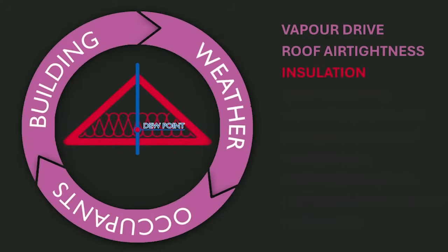As this is influenced by both the temperature gradient and the vapour drive, the specification of the insulation has a significant effect. As the level of thermal insulation increases, the outer layers of the roof will become colder with correspondingly higher condensation risk, all else being equal. Conversely, a more vapour-resistant insulation will limit the quantity of moisture which is able to reach these colder areas, lowering the risk.